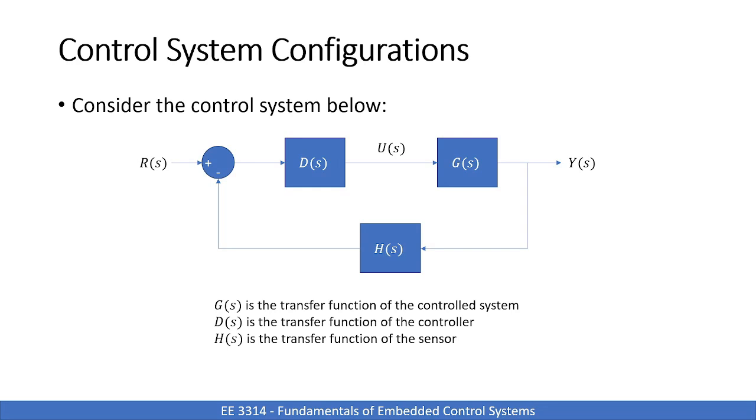It's measuring the temperature in the room and feeding that back into our control system, so the left side of H of S is degrees. I'm not set up to draw, but you'd have degrees here on the left. So your error is going to be desired degrees minus actual degrees, and that error is what's going to go into your controller, right?